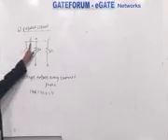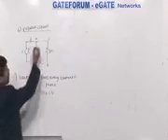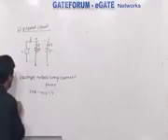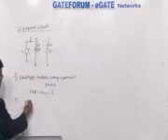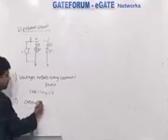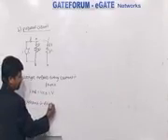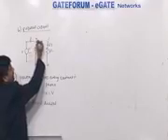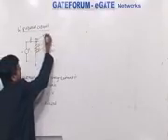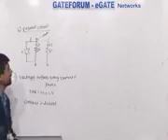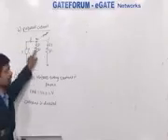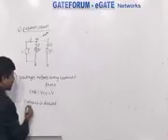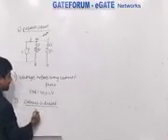Now, what will happen here? If current of I ampere is flowing up to this point, current will be divided as I1, I2. So, current is divided. Now, this is the common point which we can treat as a node. Node is a point where number of branches will meet. This is one branch, this is second branch, this is third branch. So, current is divided. KCL is applied.